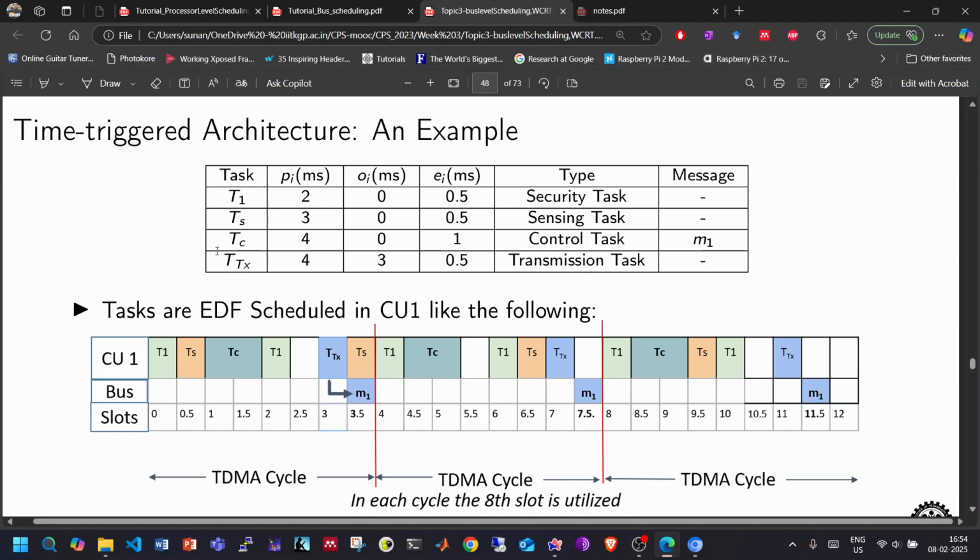When we say we are doing something in an asynchronous way, that means I will keep on transmitting periodically. It does not matter if I am done with the control computation or not, because that is what I should keep on doing. I have to keep on transmitting. I should not be bothering about that. So if I keep on doing that, how should I ensure that I am transmitting the correct data? For that, I will add an offset to the task.